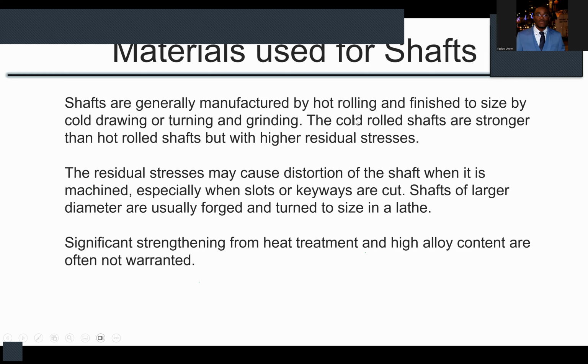So I think I've talked about this: shafts generally are hot rolled, and then they can be cold drawn. Cold drawn shafts are way stronger than the hot rolled shafts, but they usually have very high residual stresses. The concept of residual stress is when you are forming the shaft, stress is generated inside that shaft member. Stress is force per unit area, and it's distributed along the length of the shaft.